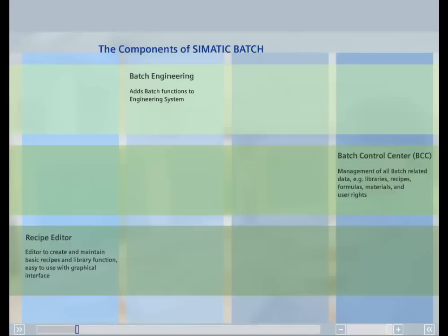create and administer recipes. The Batch Basic Package consists of 3 components: the Batch Server software, a Batch Control Center, and a recipe system. Additional Control Center and recipe system packages can be ordered individually. The server software is installed on the batch servers and supports up to 150 batch process objects, PO. Options and power packs are available to increase the PO support to 300, 600, 1800, or unlimited process objects.